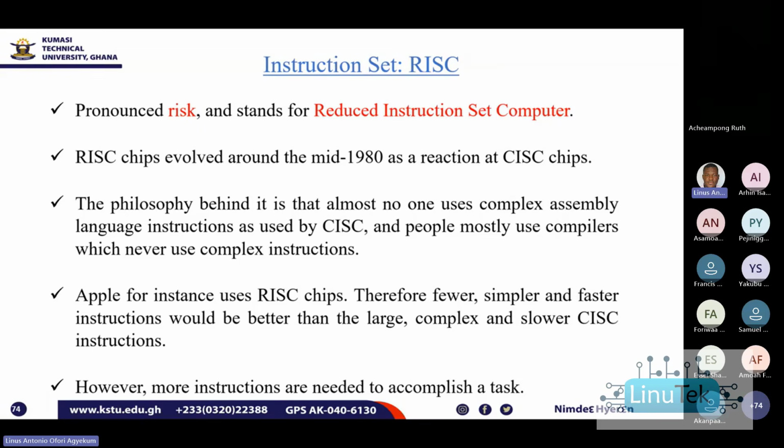And the philosophy behind their evolution is that almost no one uses complex assembly language or machine language directly, as is used by the CISC architecture. And so, because people use compilers and high-level languages, there was no need to put burden on the hardware. So, in this case, you write simpler instructions, but plenty of them.